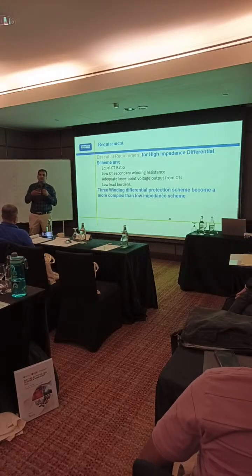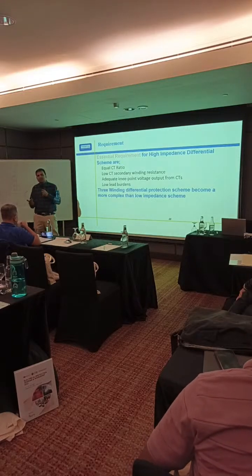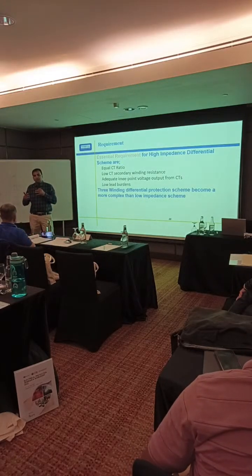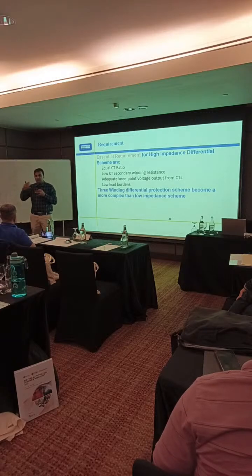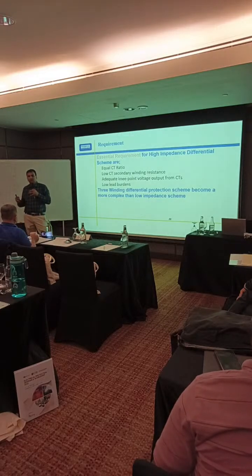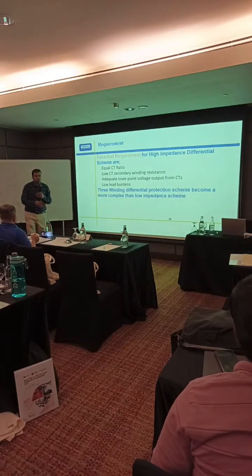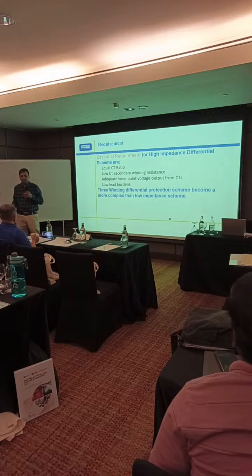Now mostly numerical relays are there, so the burden requirement is not much. If you ask for a knee point voltage to handle so much load, the cost of the CT will also increase. So that is why mostly this high impedance differential protection is not used anywhere.